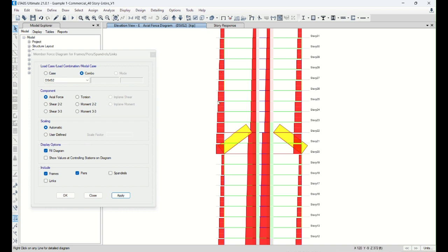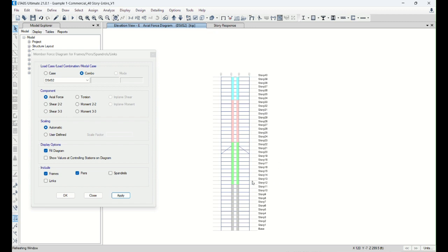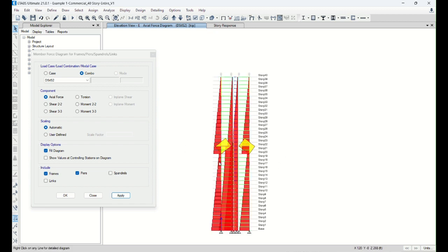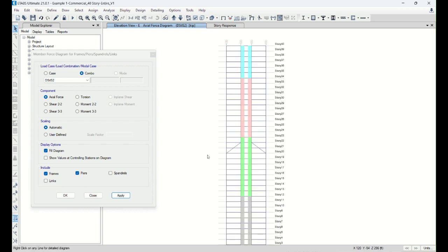Previously, this compression force was continuously growing, but now because of these sizes, the bracing elements are holding it back to the core wall, so a lot of tension develops here, which means less compression force going down. So with this model, obviously, if you're using this current model, you have some kind of issue.